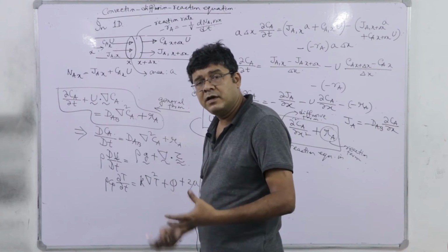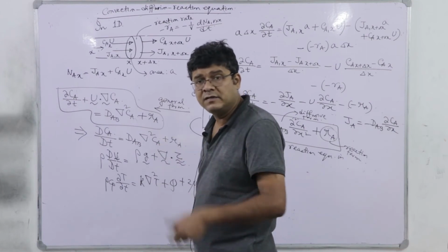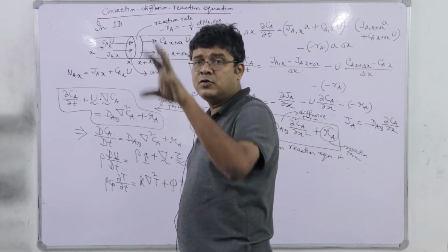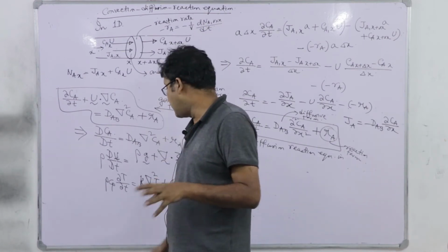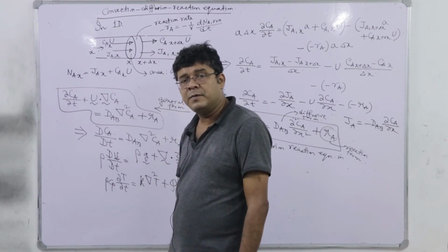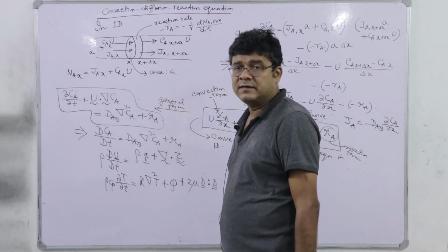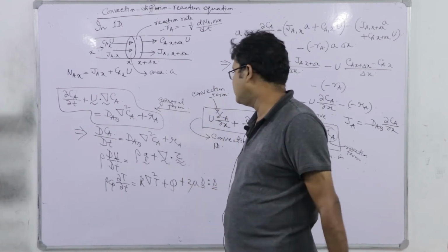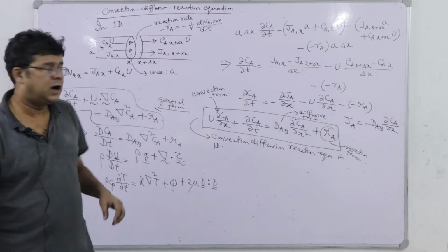So, it is a kind of either mass concentration or momentum concentration. Rho into V is the momentum concentration, because its unit will be kg per meter cube into meter per second, so kg meter per second divided by meter cube. Rho Cp T is the energy concentration in the particle, in joule per meter cube. So, these are the material derivatives of these concentrations of different terms, that may be mass, momentum, or energy.